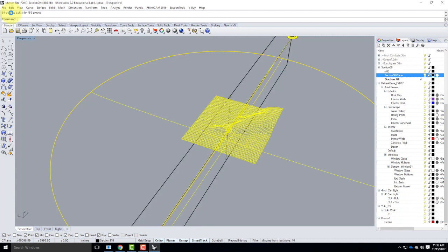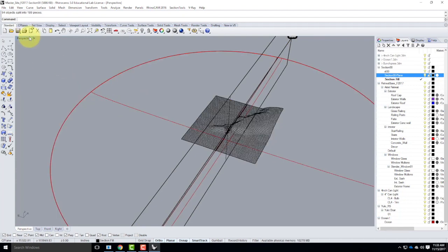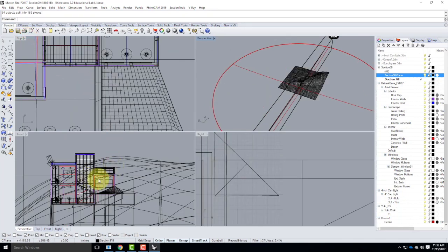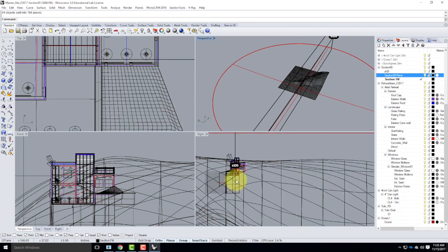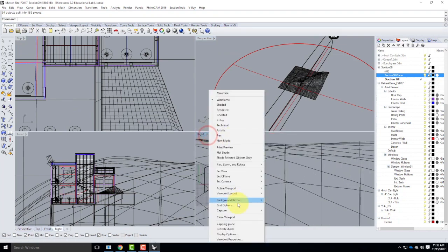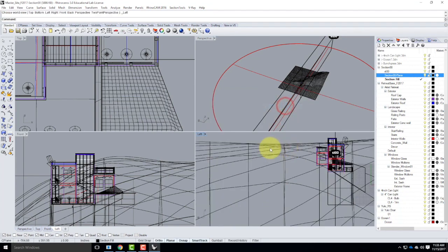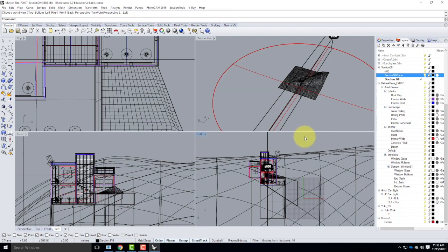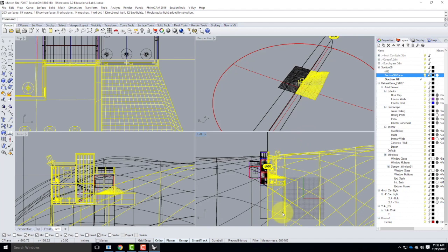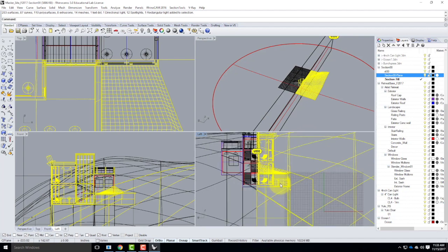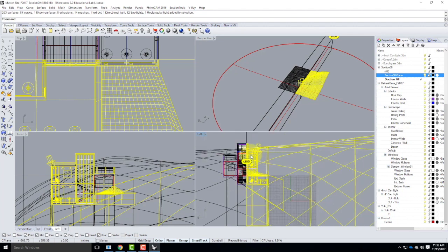All right. So a bunch of my stuff was split, which is a good sign. Now, if I were to view this in my right side elevation, actually, let me switch to my left side elevation because it's going to make the selection process a little bit easier. And if I were to select the stuff that is on this side of my big split line, see how my selection is stopping halfway through the building? That's a good sign. That's the way I want it to. So I'm confirming that, yes, this is actually working the way I want it to work.